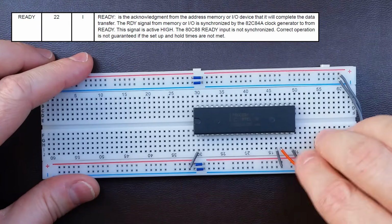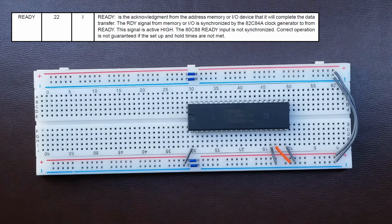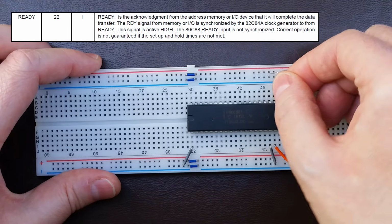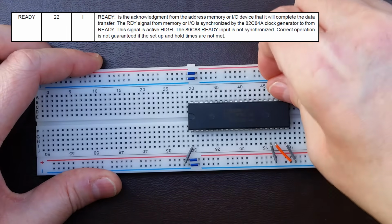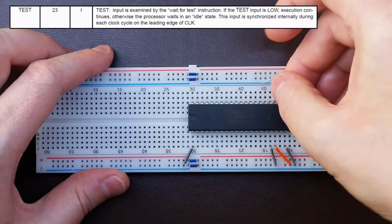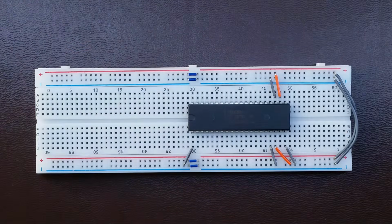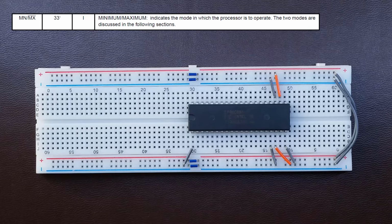Pin 22, READY, is an input which is active high. It is a signal from the peripheral or memory when it is ready to be read from or written to. We can set it high for now. Pin 23, TEST, is an input active low. The processor has a special instruction WAIT which halts execution until this pin is in the active state. Let's pull it down to the ground then. The next 8 pins have dual purpose and their meaning depends on the state of pin 33. That's because the CPU's bus can work in 2 modes called the minimum and the maximum modes.